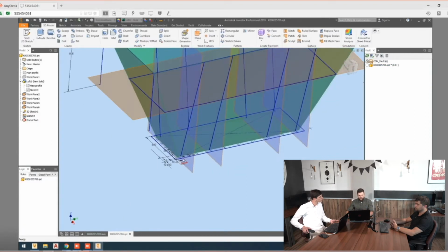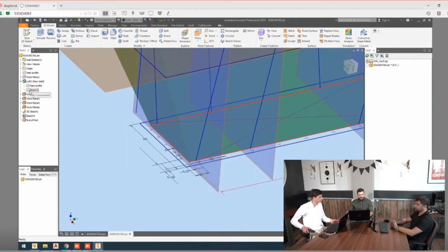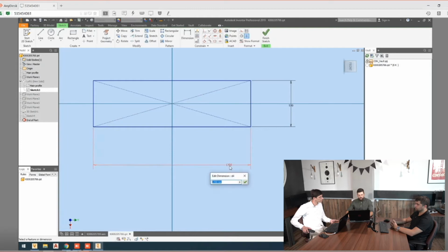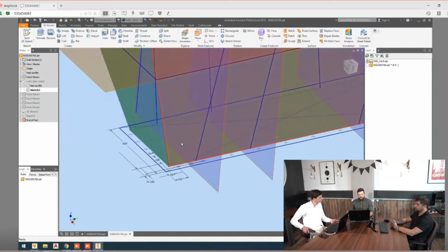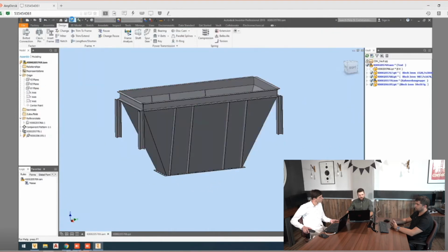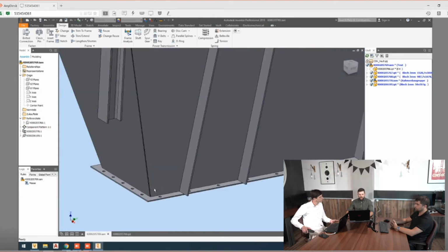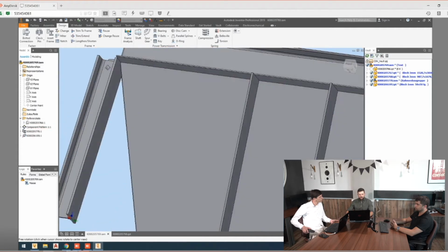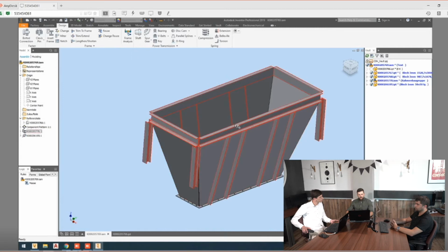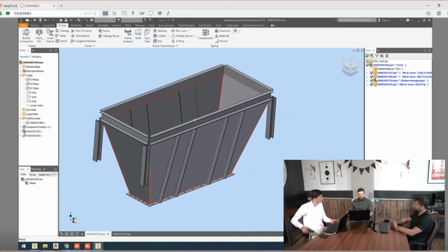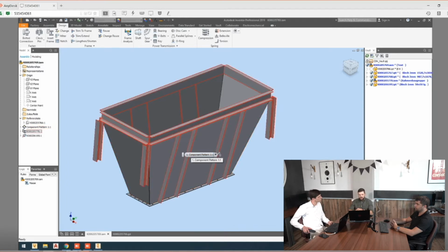And I can also, for example, change the bottom flange like this, so that maybe you can better see how it looks. And then I will refresh again. Yeah, and you can see that it updates automatically. And all connections stay the same, and you don't have any problems with intersection somewhere. So this is the idea of how you can use this basic part to create big constructions with a lot of sheet metals, a lot of parts.